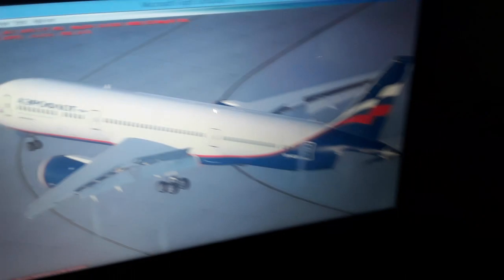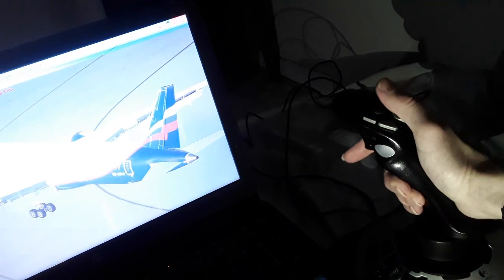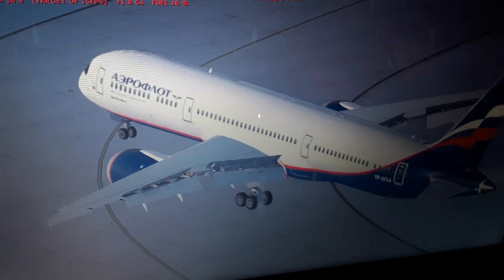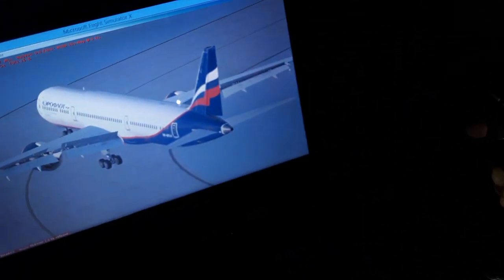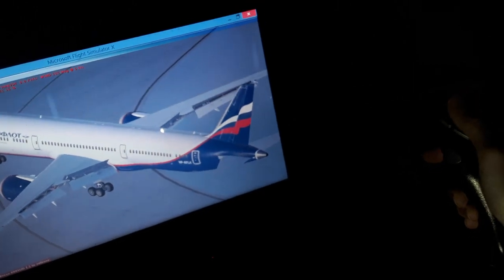Then as we go to like 80 nautical miles per hour in takeoff or inverse in landing, we have the rudder only aerodynamically effective, and the nozzle steering is deflected at 0 position. It's locked at 0 position, so there is no nozzle steering above 140 kilometers an hour, 80 nautical miles per hour, both takeoff and landing. So we have only the rudder aerodynamically effective.